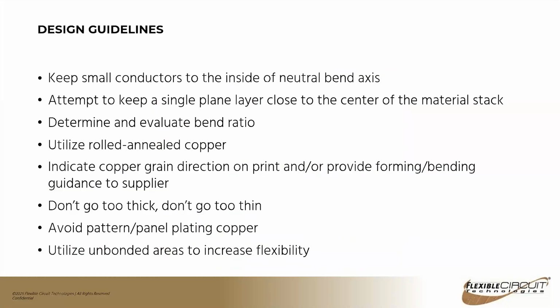So some good design guidelines to follow if you know you're forming a circuit or have a dynamically bending application: keep small conductors to the inside of the neutral bend axis. If you had a double-sided part with signals on one layer and a shield on the other, it's best to design those signals on the inside of the bend radius. Attempt to keep a single plane layer close to the center of the material stack, which we saw in the very first slides with that single-sided example.